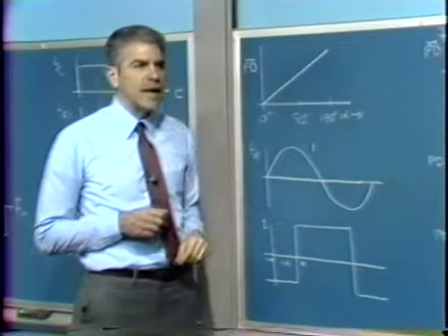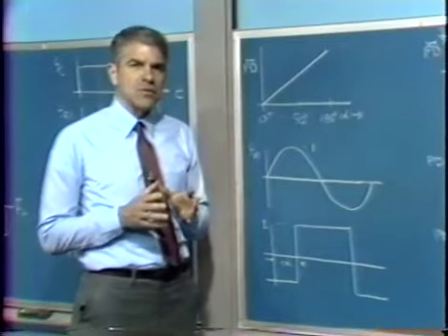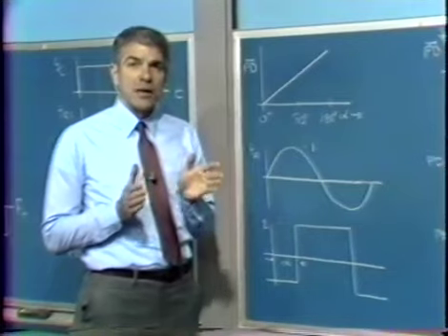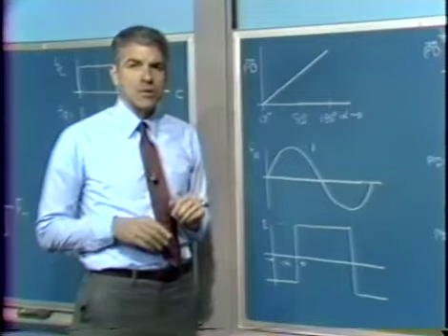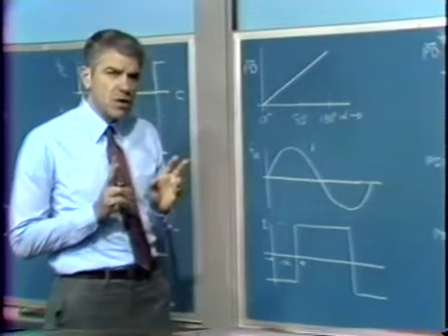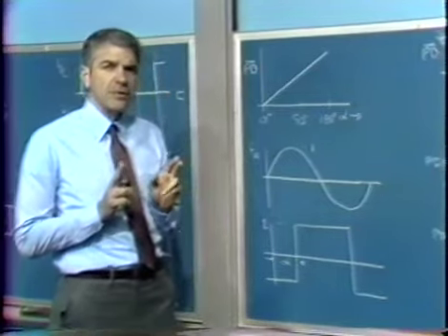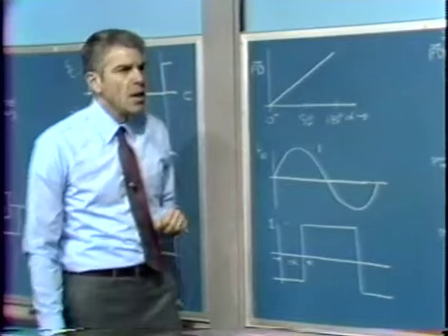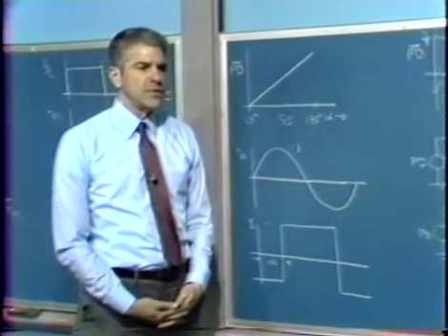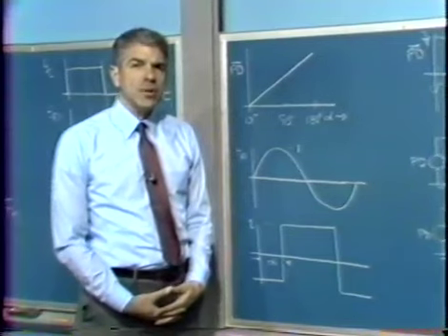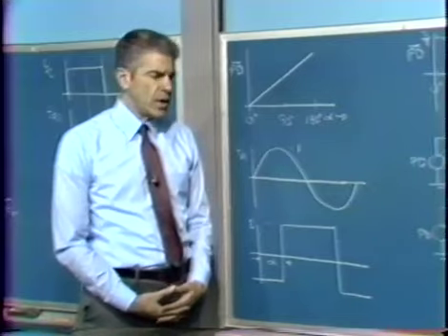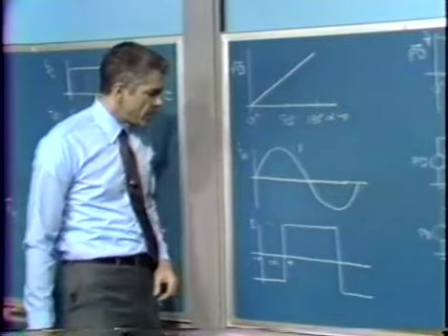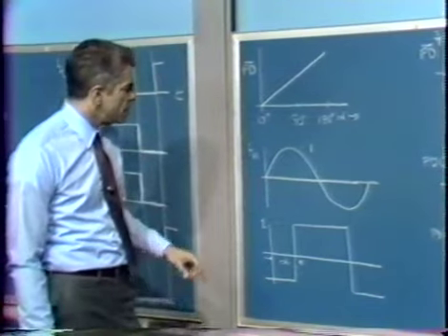We'd once again average that output. And if we chase through the relationships, assuming we're setting on one of our signals and resetting on the other, we'd find out that the average value of the flip-flop output would be proportional to the relative phase difference between the two digital signals. For an example of this sort of system, we're going to look at a commercially available integrated circuit phase-locked loop, a type 565, which has been around a while. It uses a different kind of phase detector.